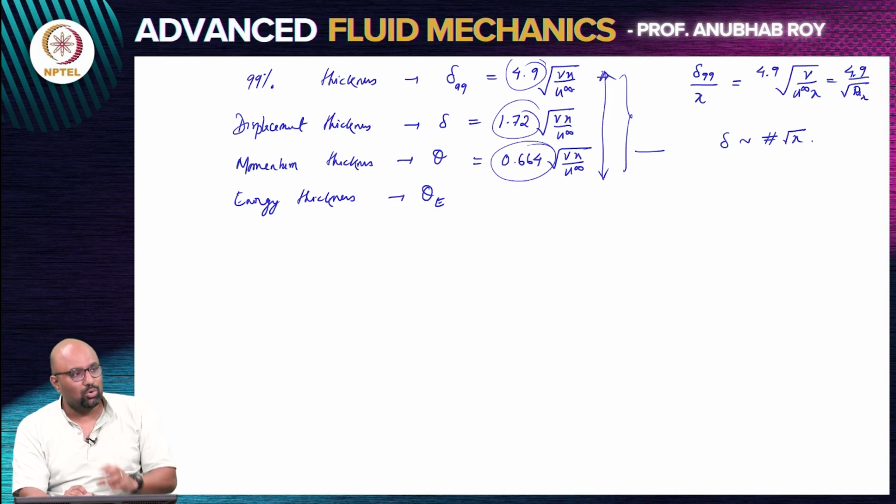What is happening due to a no-slip boundary is all that I have described here, that the velocity will not match the free stream. Streamlines are going to get displaced in order to compensate for the mass flux. There is going to be a momentum deficit.